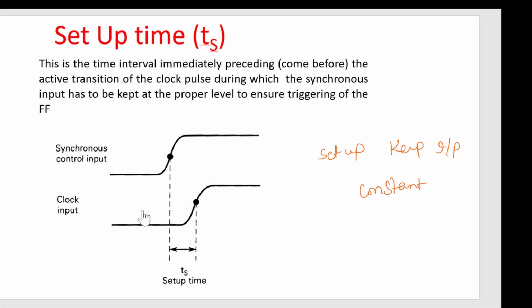Please remember, look at here, this is your clock input, and this is your synchronous input, that is your data input, and your setup time is defined from the 50% of your waveforms all the time for the clock as well as data also. If you look at here, from this point to this point, during this period your input should be maintained at a stable output level.